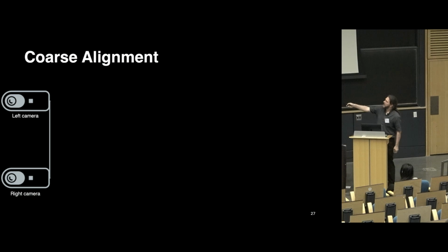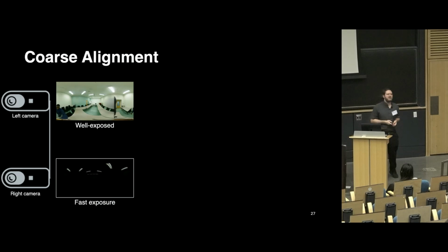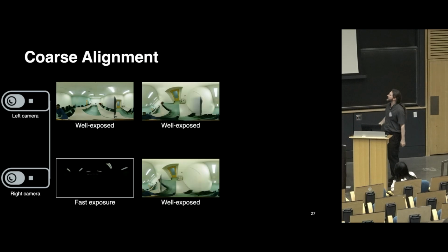The fact that we have two different cameras makes this setup stereoscopic. And unfortunately, those cameras are not exactly at the same location, because those are two physical components that we cannot embed into one another. And we need to understand the distance and the rotation between those two cameras.